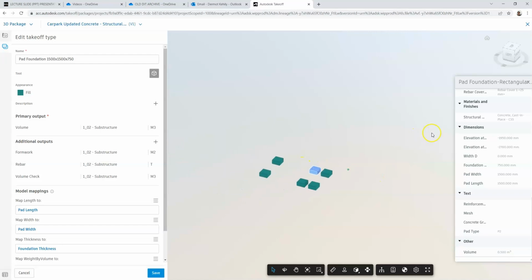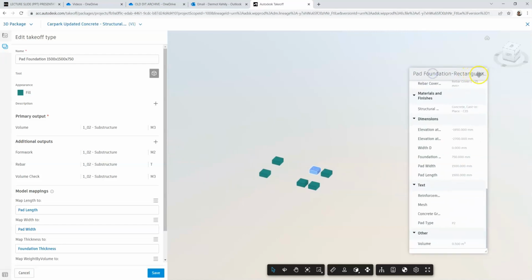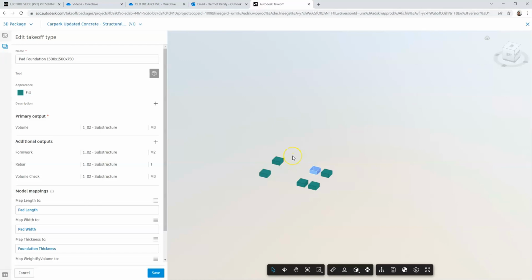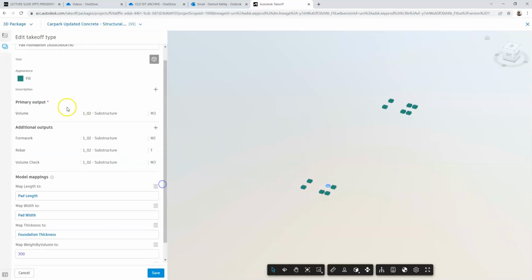Quite possibly just some sort of calculation error when the export happened, or in the Revit model, or something the architect did. So this is a good example of the fact that you have to interrogate your model, you have to validate it, and you have to double check your quantities. You still are the owner of those quantities, and you are the calculator of those quantities. Just because you got it in the BIM model, you can't point the finger at the architect and say something is incorrect. So I've done a check there, and you'll notice in other object properties and other takeoff items, I'm doing similar checks. And once I export that now, I can link to those quantities.